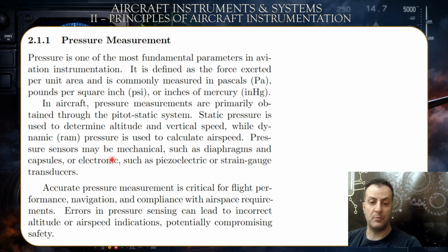Pressure sensors may be mechanical, such as diaphragms and capsules, or electronic, such as piezoelectric or strain gauge transducers. Okay, we're going to understand it better in the further slides. Now, accurate pressure measurement is critical for flight performance, navigation, and compliance with airspace requirements.